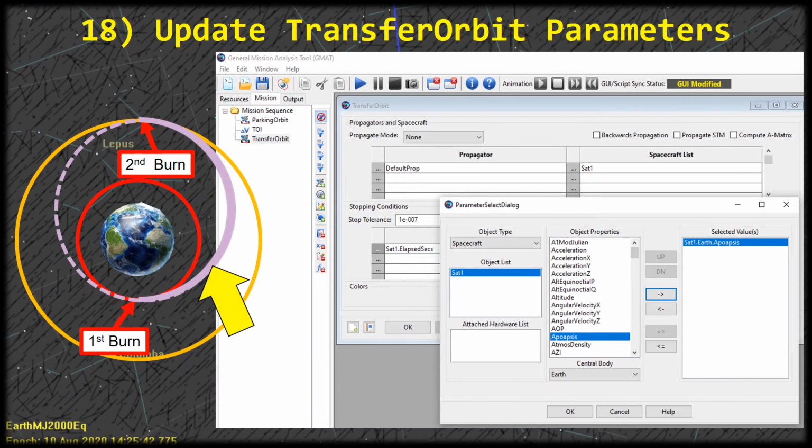So go ahead and double click on that TransferOrbit to open the propagation properties window. And we're going to go ahead and change the stopping condition by clicking on these 3 circles on the left. And we're going to change it from elapsed seconds. We want to propagate this spacecraft to the apoapsis point of the transfer orbit.